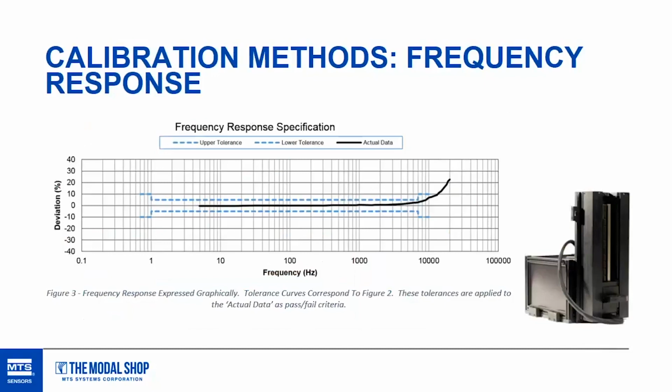And finally, I'll talk about why do people get a high frequency calibration? Why do they get a low frequency calibration? Should I be getting both? It really depends on what you're interested in, what type of testing you're doing. If you are testing windmills and you're really interested in the accuracy of that low frequency data, what's happening at 1 hertz on my structure, people opt for low frequency calibrations in that case.